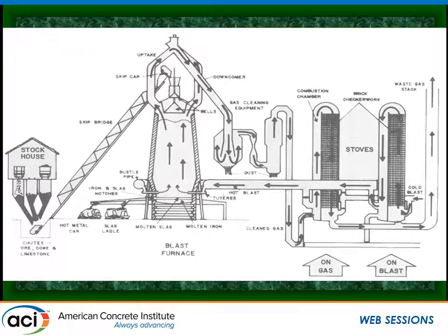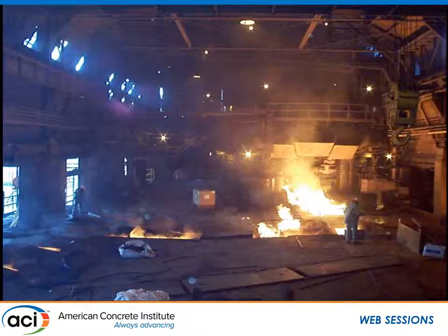And the biggest difference is that instead of a long horizontal revolving kiln of fire, we have a static vertical blast furnace of fire. Same process where we're breaking down the material, we're crushing limestone. Limestone is used as a flux in the melting and the reduction of the iron ore. It's going to be iron ore, limestone, and coal. That's going to be put into the blast furnace, broken down, and we tap the blast furnace.